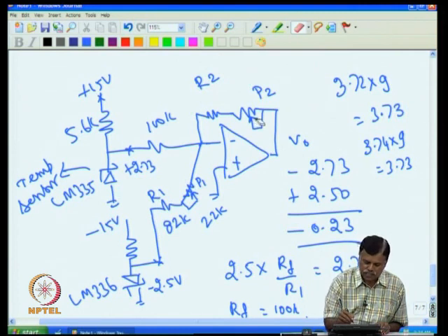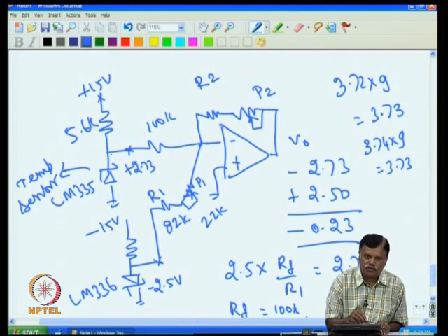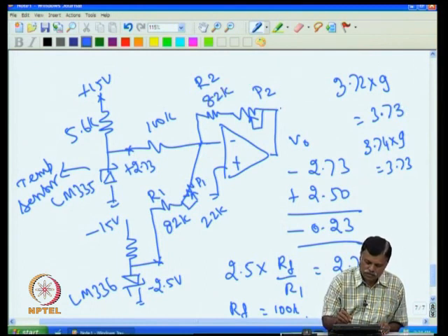So normally what is done is, I will keep this one somewhat fixed because the variation here is not going to be very high. Normally within 1 or 2 degrees only you will get it across the sensors. So I can keep this one 82k, and then I put here, for example, 22k. That will give me a maximum of 104. If I want, I can also increase the value, so that it is easily adjustable.